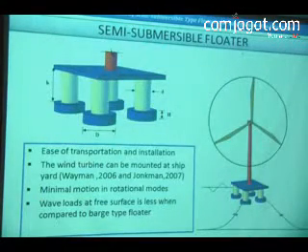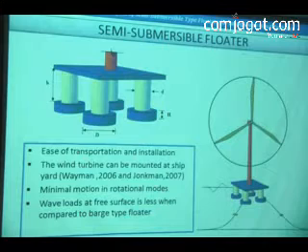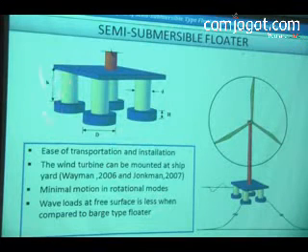What we took is three different types of floaters: a barge-type floater, a semi-submersible floater, and a deep-drafted column-structured floater. This is part of the results for the semi-submersible type floaters. It's different because we have four pontoons, and we had a parametric study varying the height of the column, the height of the pontoon, the diameter of the pontoon, and the diameter of the column. That was the structure we had in mind for supporting the offshore wind turbine.